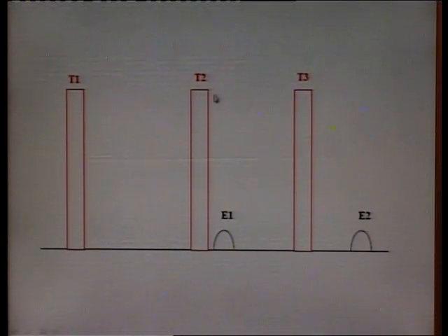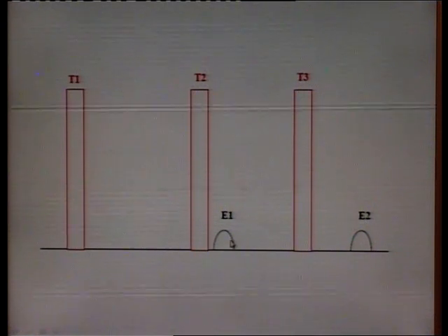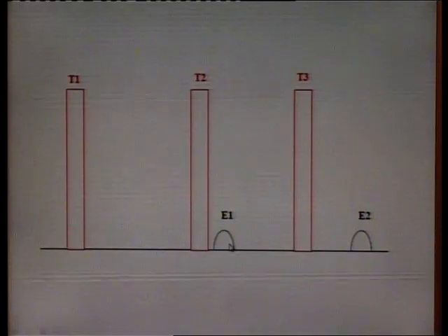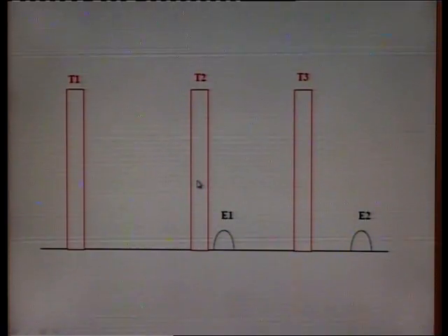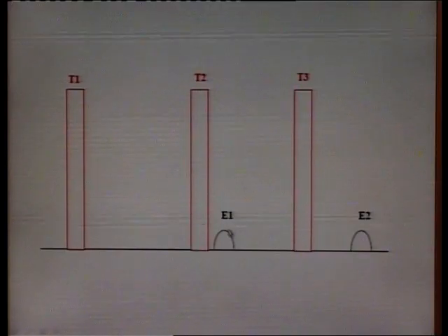Again a signal is transmitted and we are waiting for the signal, and here the signal comes. Now, this received signal has come, but we are not sure where it has come from, whether this is the reflection of T 1 or the reflection of T 2. It is not known. So, this gives a confusion, which is also called ambiguity.